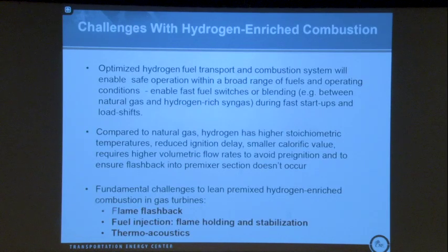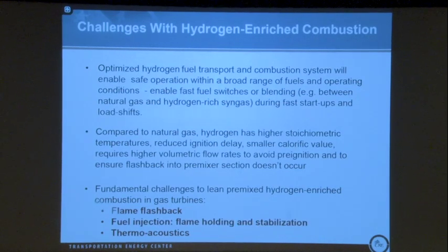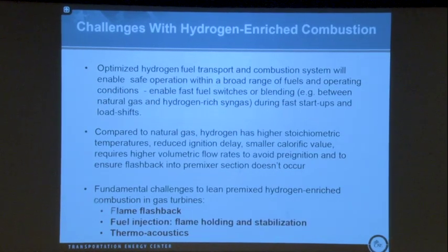The problem with burning with hydrogen-enriched combustion that's different than natural gas, though, is an issue of safety primarily, because hydrogen is so reactive, has such broad flammability limits and such short ignition delay times.